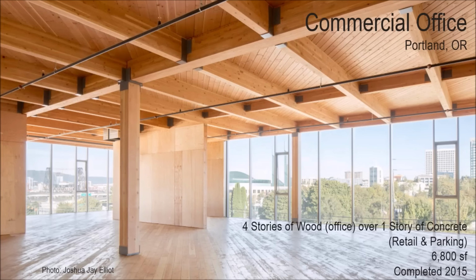But this project here, while it doesn't have CLT, it has a tongue and groove floor system over a post and beam frame, but you can imagine that being CLT as well. In this project, four stories, Type V construction, what they used as their vertical seismic force resisting system is a light frame wood structural panel shear wall. Perfectly acceptable to mix and match.